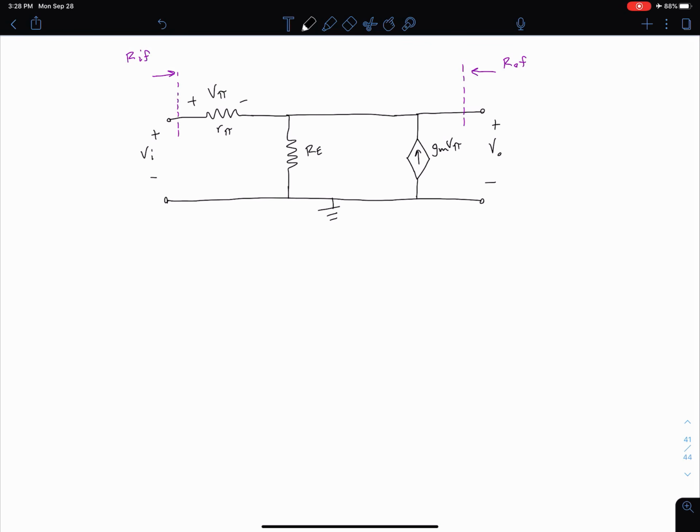So what we're going to focus on here is our transfer function though. So we want to see how this compares to our ideal feedback equations, and what we already know our beta sub V equals 1, but we want to see if we can find the same form for this closed loop gain as we had for our ideal topologies. So we know in general that our closed loop gain is going to be the output divided by the input.